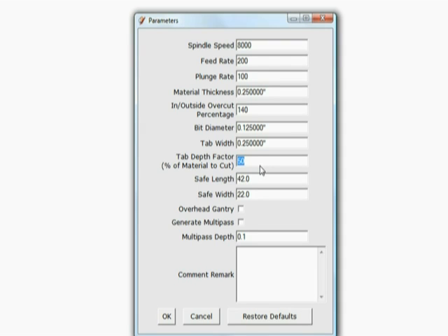Well, we find that with flat printers, that means that you're most certainly going to have to take your X-Acto blade or some razor or something to cut all of the pieces out. Now, if you change that value to say 50%, to where basically you've got a 1/4 inch wide tab, but now it's only 1/8 of an inch thick with foam in those tab areas, well, then you have a greater opportunity to just punch the part out when you're finished. Or if you have to cut it out, it's just a quick slit with the razor, and it just cuts it away. 50% is really good, I know, for the material that I'm using.